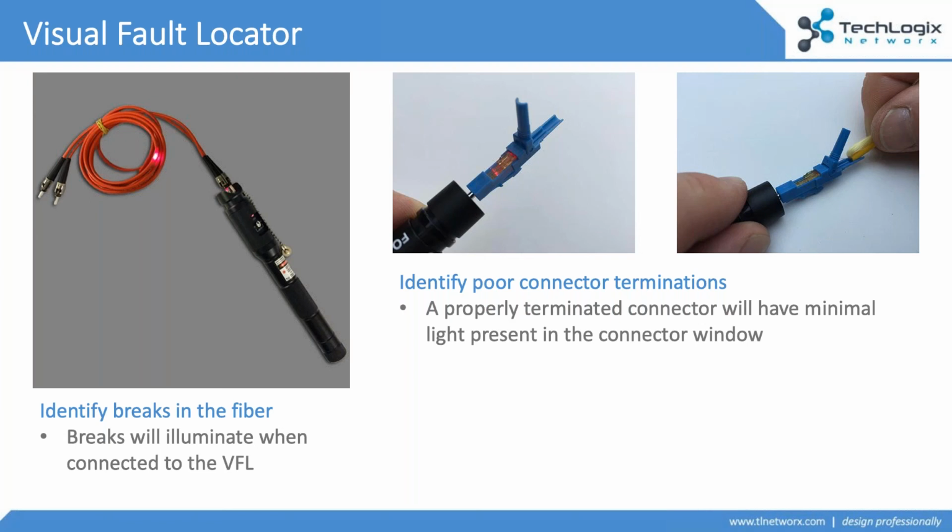And this is why you're seeing the rise of SSF grade fiber. Stronger, safer, faster. It's a polymer-coated cable that can literally be tied in knots. It doesn't break like traditional fiber optic cable does. It has a much tighter bend radius. We'll look at that here in a minute. In my opinion, the SSF grade fibers are what's making fiber optics deployable in the AV installation today. So it's just what we are seeing. It's what I recommend. You don't have to worry about those breaks in the middle of your cable because it's far more impervious to that.